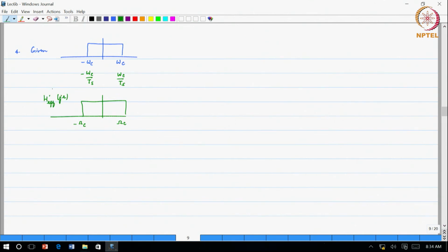of j omega. Okay. Now, I want to have the condition that there is no effect of aliasing, no effect of aliasing, it is not no aliasing. Please note that I am only saying that I know that I am going to do some filtering, and it is going to kill all frequencies outside of omega c, mod omega c.